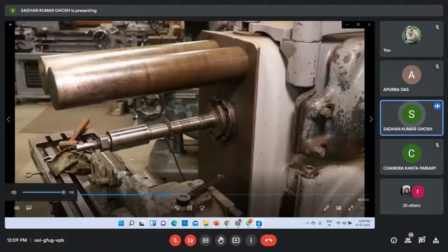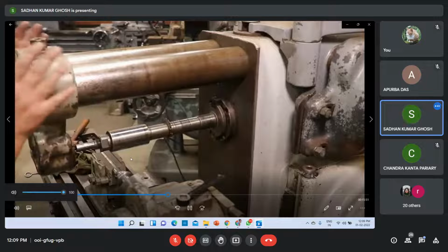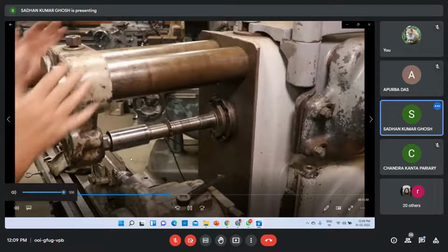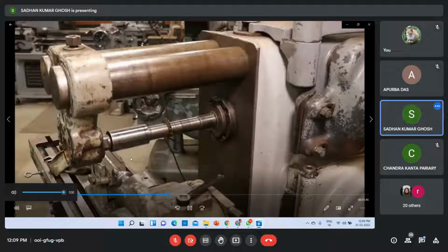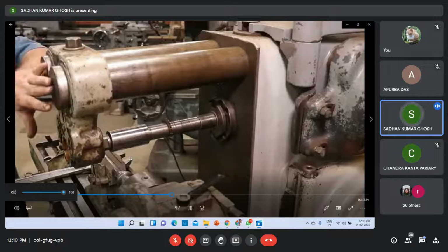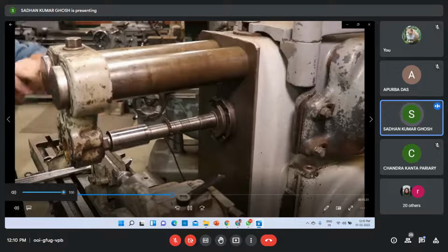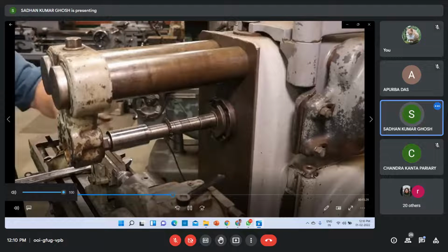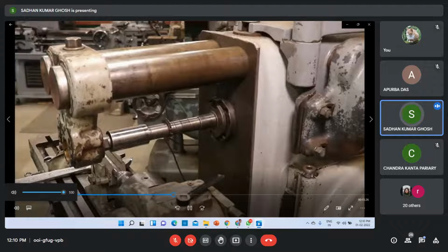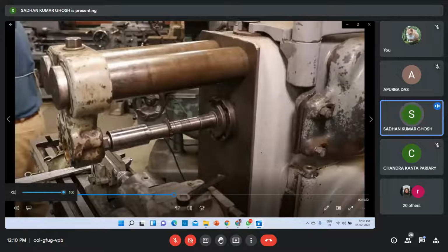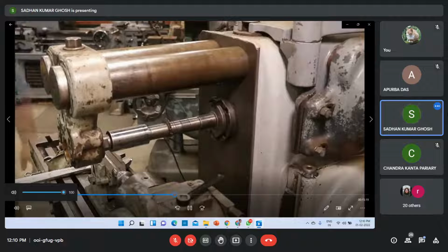And then we'll take our overarm support and put it onto the top up here. I like to go ahead and tighten that down. And now, trying to get it lined up on 3 points, the bushing as well as the overarms all at the same time, we'll just pull it onto the bushing and it'll kind of self-align on there. But before I do, I'm going to squirt a little oil up in there just to get me started with some.